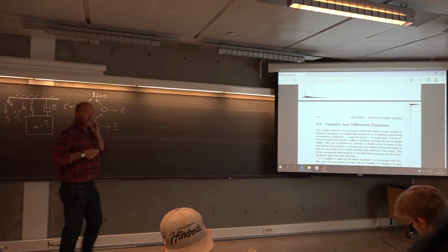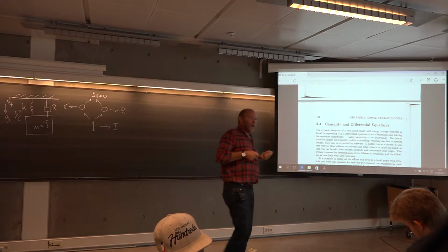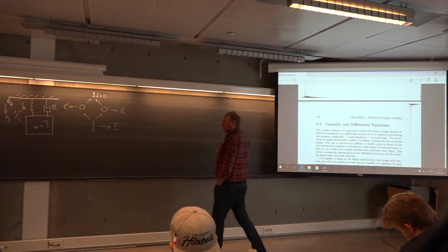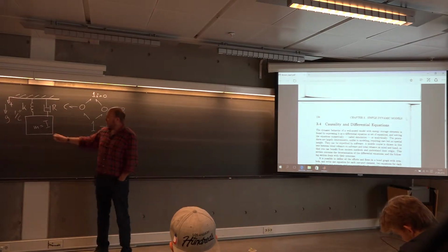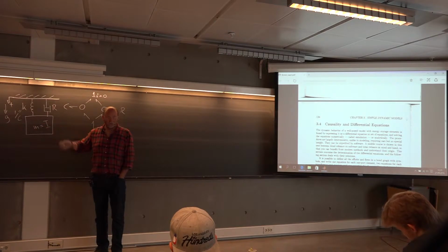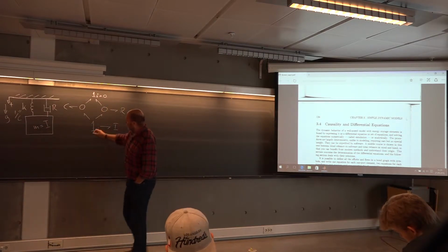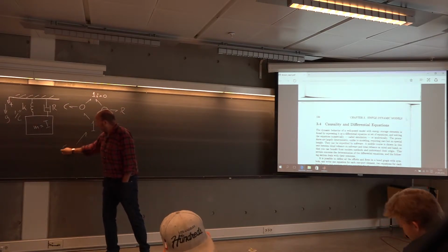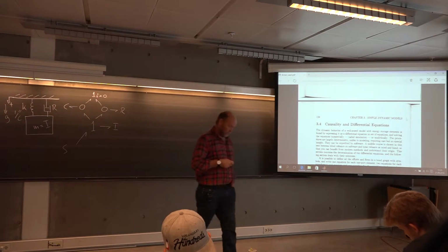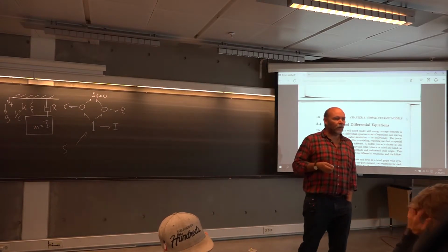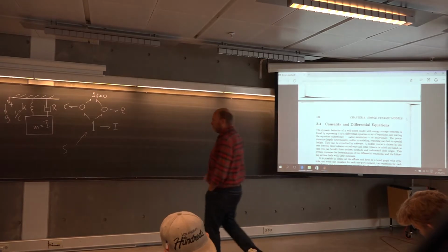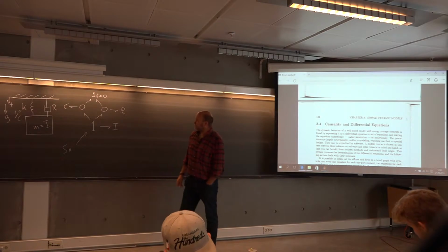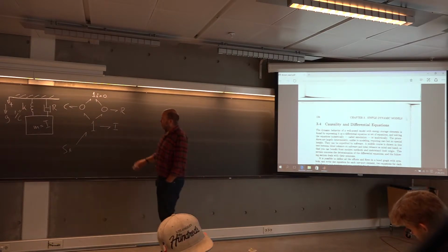Now we are missing something. Where's the gravity? Well, the gravity is attacking what? It's attacking the mass and only the mass. So for this one junction here, he is attacked by a source. What kind of source? Well, gravity will provide a force, an ideal force. So this is an effort source. That is the raw bond graph.